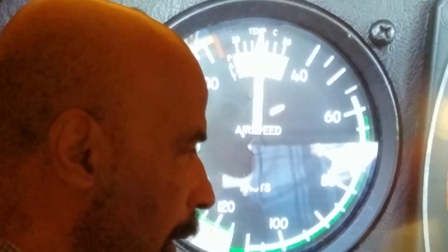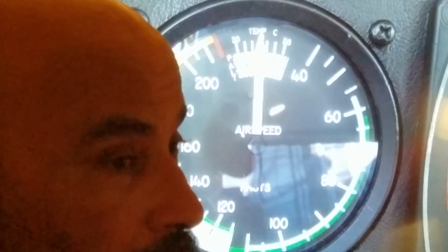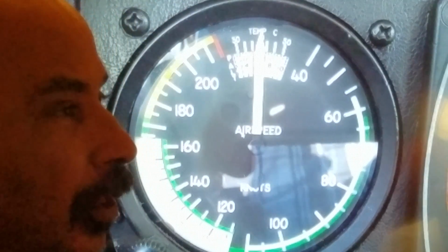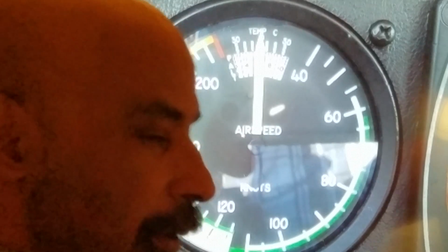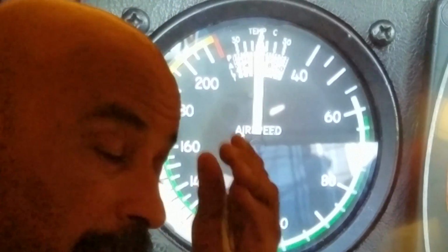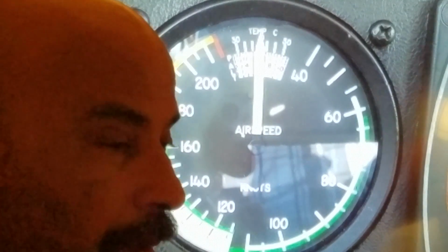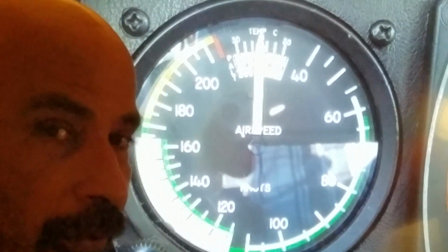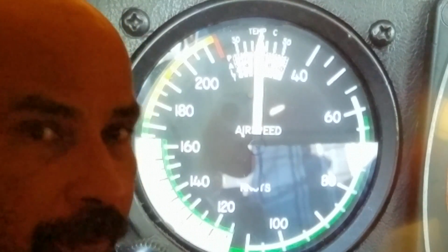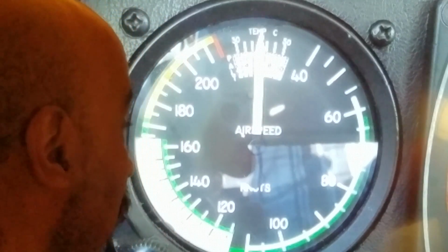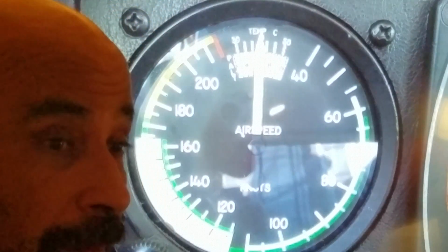And they both, this gauge and the next gauge, the attitude indicator, this airspeed indicator, if the pilot becomes so dependent on the airspeed indicator, and has trained to depend on it to the extent that he loses the feel of his aircraft, anything can fail. And if this gauge fails, then the pilot without the feel of his aircraft would tend to, well, be confused about what his aircraft is really trying to tell him.